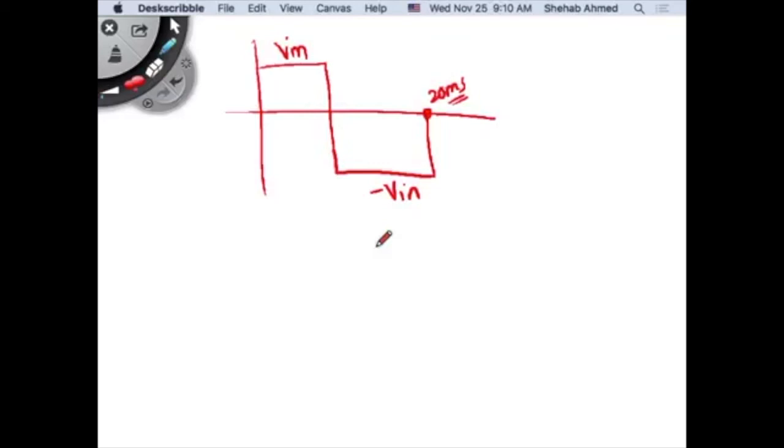But here, it's a square wave voltage. If I have a resistor, square wave current, no problem, life is great, right? But if I have an RL load, the current will not look exactly like the voltage. So there will be some content in the current waveform that is not in the voltage waveform, so I will have some losses there. But assuming it's a resistive load, then this is perfectly fine. The problem is it has a lot of harmonic content.